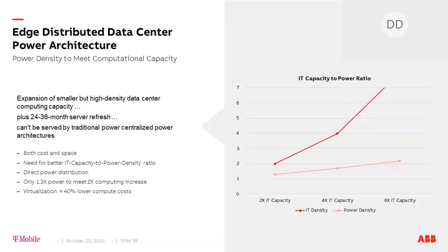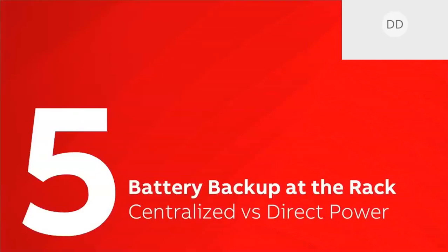So you can save money on the equipment as well as on the power usage. That's great. So one of the obvious advantages of this system is the elimination of the centralized power system and its construction costs, whether it be AC or DC UPS. But the implication is a much reduced battery backup capacity. You've specified 2 minutes in your systems.